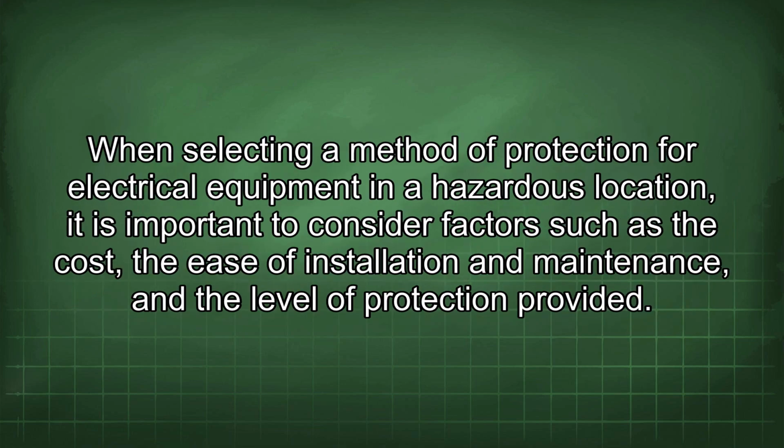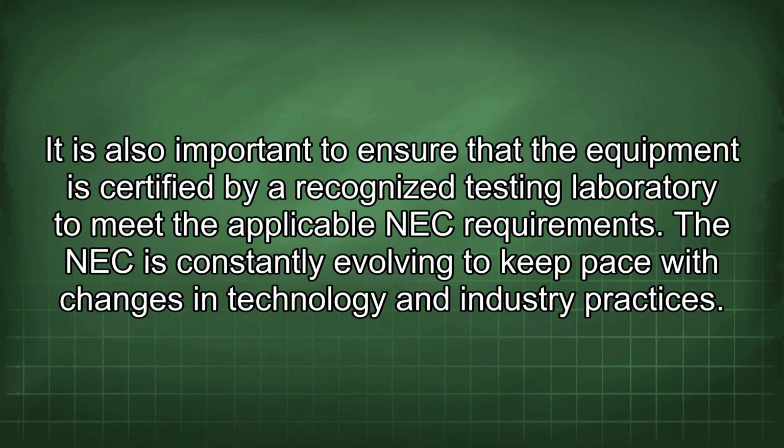When selecting a method of protection for electrical equipment in a hazardous location, it is important to consider factors such as the cost, the ease of installation and maintenance, and the level of protection provided. It is also important to ensure that the equipment is certified by a recognized testing laboratory to meet the applicable NEC requirements. The NEC is constantly evolving to keep pace with changes in technology and industry practices.